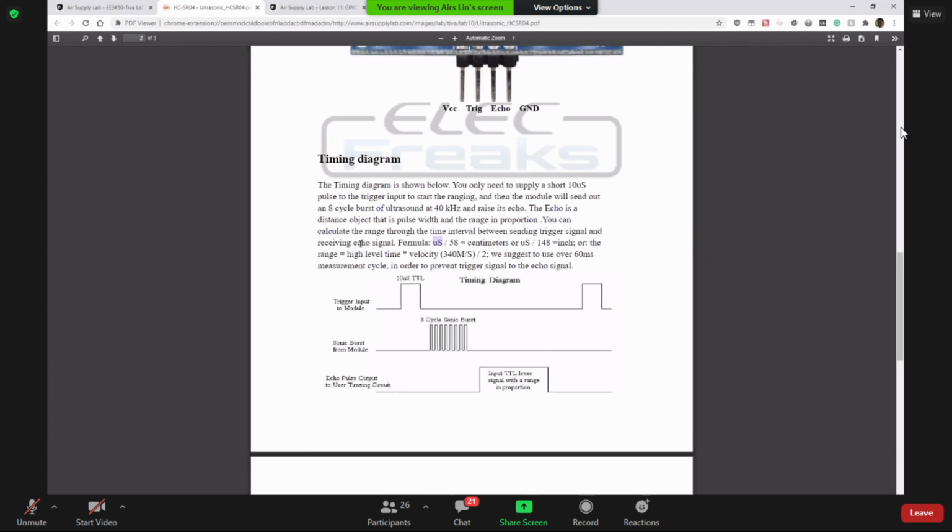The first one is the UART. You need to configure UART. The baud rate is 38400, with 8 bits, one stop bit, and no parity check. The second one, you're going to finish the code to determine the sensor signal pulse width. And the third one, you're going to use the PuTTY terminal.